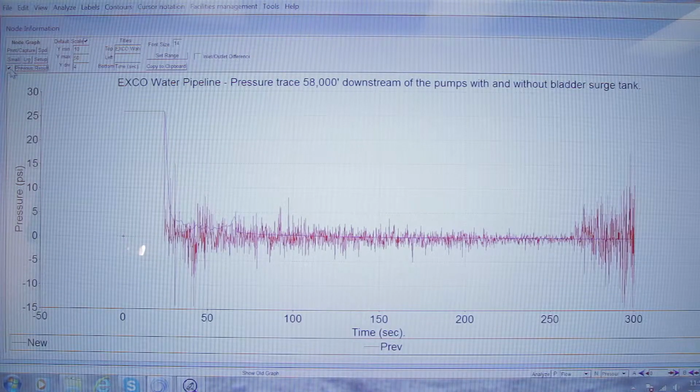So in this case, pressure, vacuum, pressure, vacuum, pressure, vacuum, we're introducing a lot of air into the system. And again, this is reuse water, or frac water, which can be corrosive. So we want to minimize the amount of air that we're letting into the line. Also, we're trying to reduce any air coming into the frac skid, because we don't want to be introducing air down 6,000 feet into the earth.